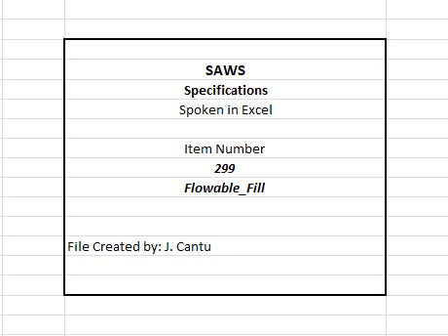C. When necessary, use specialty type admixtures to enhance the flowability, reduce shrinkage, and reduce segregation by maintaining solids in suspension. D. All admixtures must be used and proportioned in accordance with the manufacturer's recommendations. E. Mix the flowable fill using a central mixed concrete plant, ready-mix concrete truck, pug mill, or other approved method.